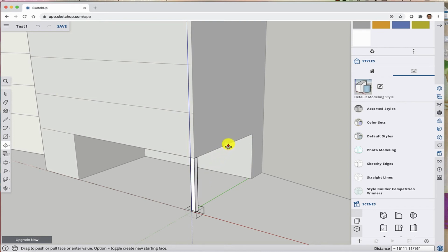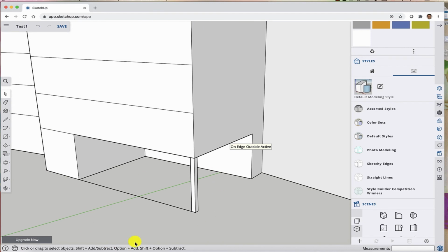And let's say I want to extrude this rectangle exactly to the height of the first level. So I can hover over this edge and click anywhere. And that's good enough for extruding that rectangle to that distance. Okay. If I click outside, I'm going to get out of the isolation mode. Now I have created my column, and now I can copy and paste it along this path.